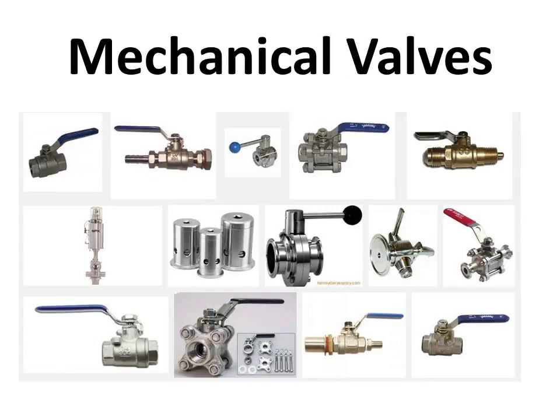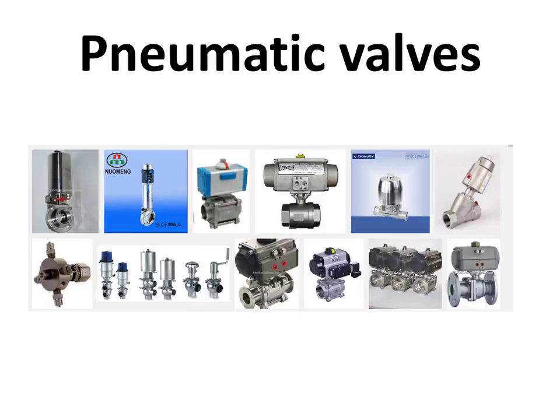Well, if you look at those brewery systems, you have mechanical valves. I went to Google Images, and here are a group of them. You more likely have pneumatic valves, which are automatic valves. You don't need to change the valve position from off to on or on to off manually. You can send an electrical signal, and the little thingamajig above the valve will turn the valve. So these valves, they're expensive, but they help you automate a brewery plant.